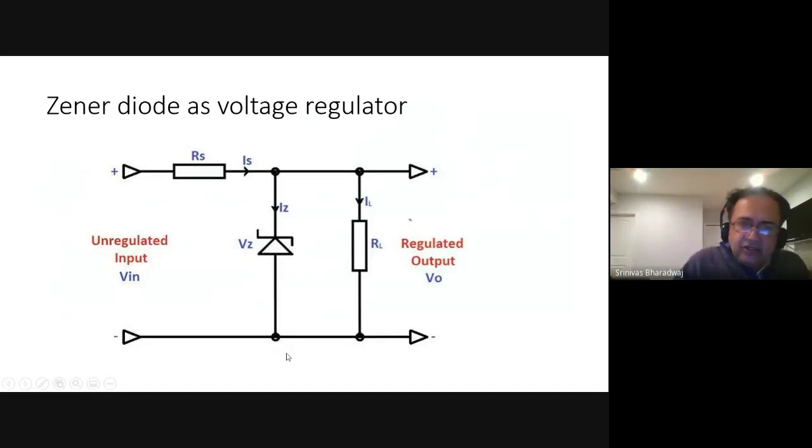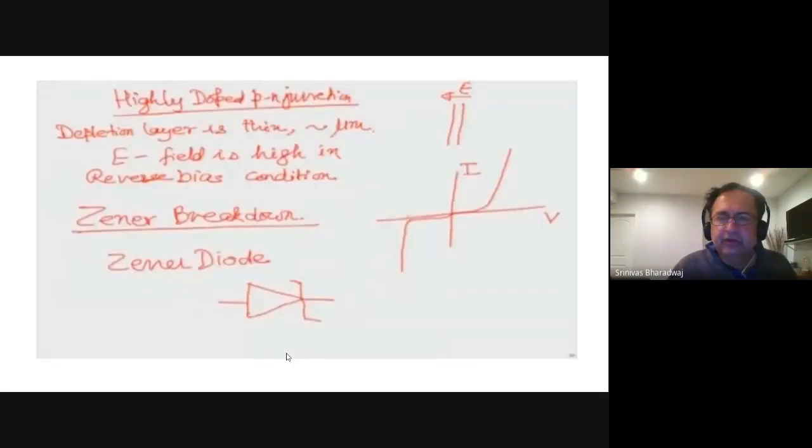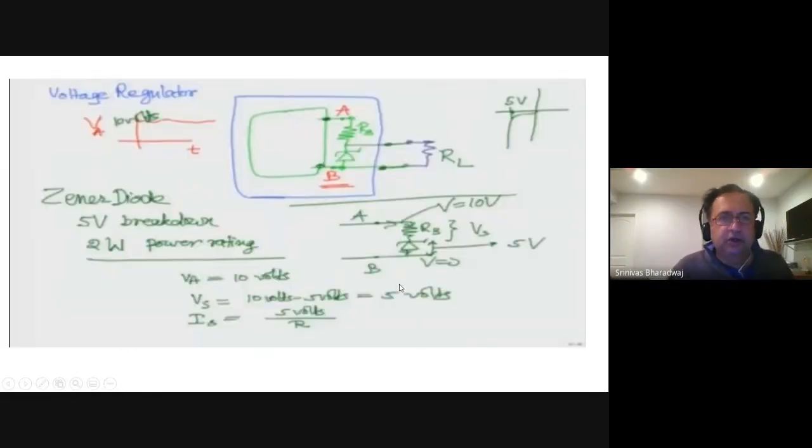The Zener diode starts to conduct, and very rapidly the current increases, and it becomes a short after the voltage goes beyond a particular value. When the voltage exceeds a particular value, it starts to conduct and becomes a short. That is typical when it is used as a protector, as a voltage regulator. Now the other setting is this way. This is the same as this one. This is the standard case. You have the power side, and you have the RB, then you have the RL.